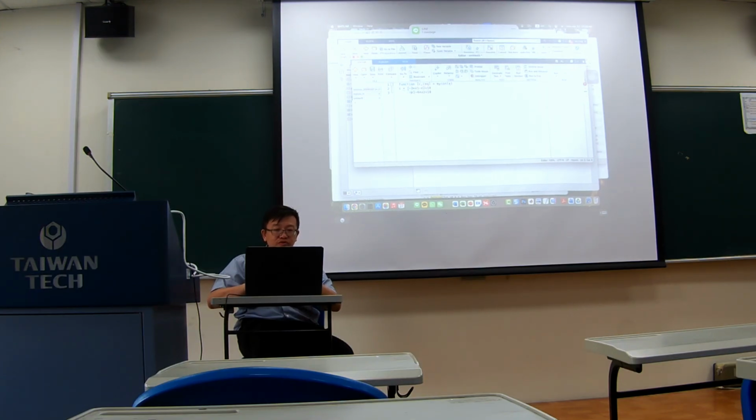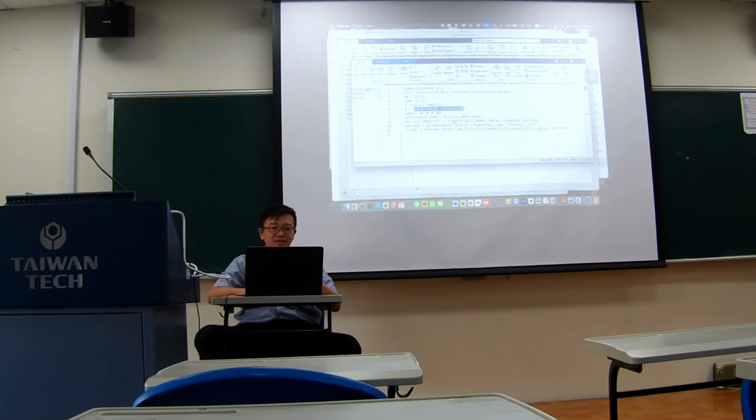So they will become two values. But like I said, for additional constraint function, MATLAB only allows one symbol for the variable. So you need to use x bracket 1, x bracket 2 to specify each function value. So for the ceq, just give an empty output. So no equality constraint. Save the file as my com. Come back here.